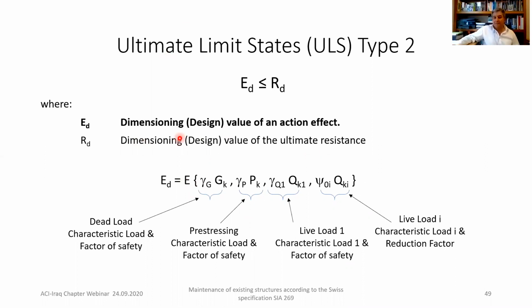That means we are using the dead load with the factor of safety of dead load. We have the pre-stressing, if you have pre-stressing, with the factor of safety of pre-stressing. And I will draw your attention that we first work with the most important live load with its factor of safety, and the rest of the live loads, the other effects, with reduction.